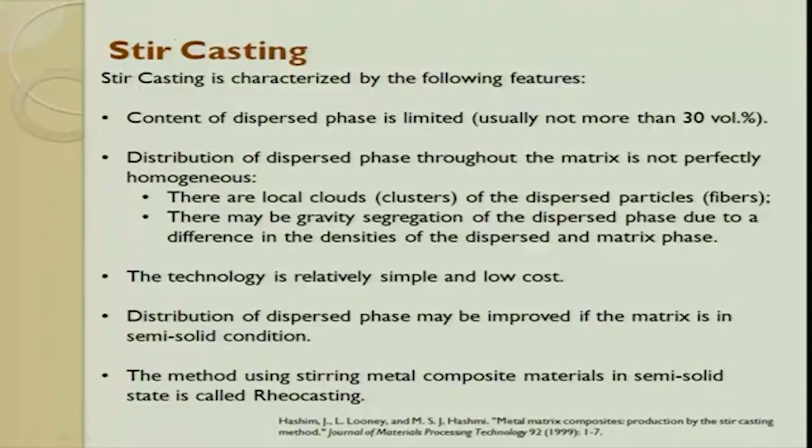Why is that very important? Suppose you want to make a really lightweight metal matrix composite. You keep adding more and more dispersed ceramic particles, and the moment you disperse them, it becomes lighter and lighter. But if you have a larger volume fraction of ceramic materials, then there is a problem of agglomeration. So in order to have a proper distribution, the maximum best possible is 30 volume fraction. However, this can be enhanced up to 60% by taking proper care and making necessary modifications in the setup. You can definitely get it done.